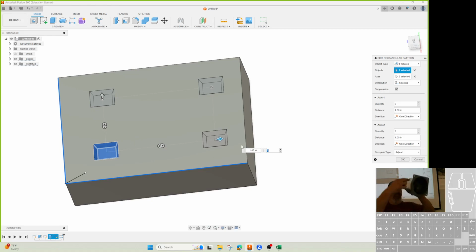So for centering, so having like 4 holes in a pattern around a thing like this, an array is not the way to do it. Okay, in that case, you'd want to rather do a sketch and do it. But on a hole, that's an easy thing. On this one, this gets a little bit more complicated. So we'd have to redo this thing. And this is where something we're going to do next week, we could just make this thing and reuse that feature.